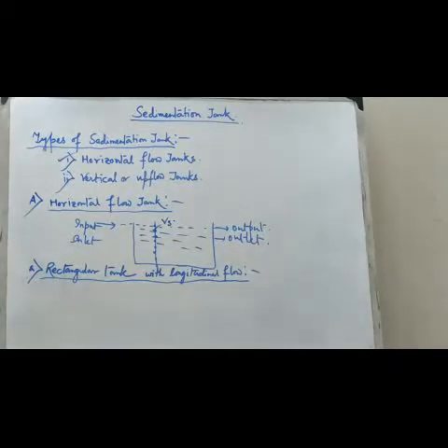This type of tank may be provided with a mechanical scraping device to scrape the sludge to the sludge pit located usually towards the influent end, from where it is continuously or periodically removed without stopping the working of the tank. Such tanks are known as continuous flow type sedimentation tanks.